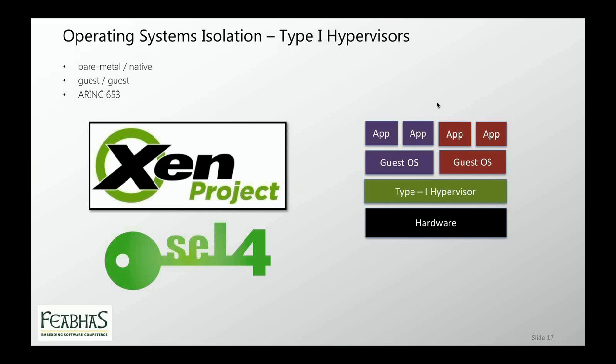And of course, those guest operating systems don't just have to be rich operating systems, they can be real-time operating systems. So it brings in this real power. For example, if you had a PC and you wanted to run Linux and Windows, one way is you end up having to reboot the machine and you boot into Linux or you boot into Windows. That's a fairly inconvenient model and obviously not appropriate for any sort of real-time control system. This allows us to have the two operating systems running actively at the same time side by side. And the hypervisor has the responsibility of doing the scheduling and management between those operating system applications.